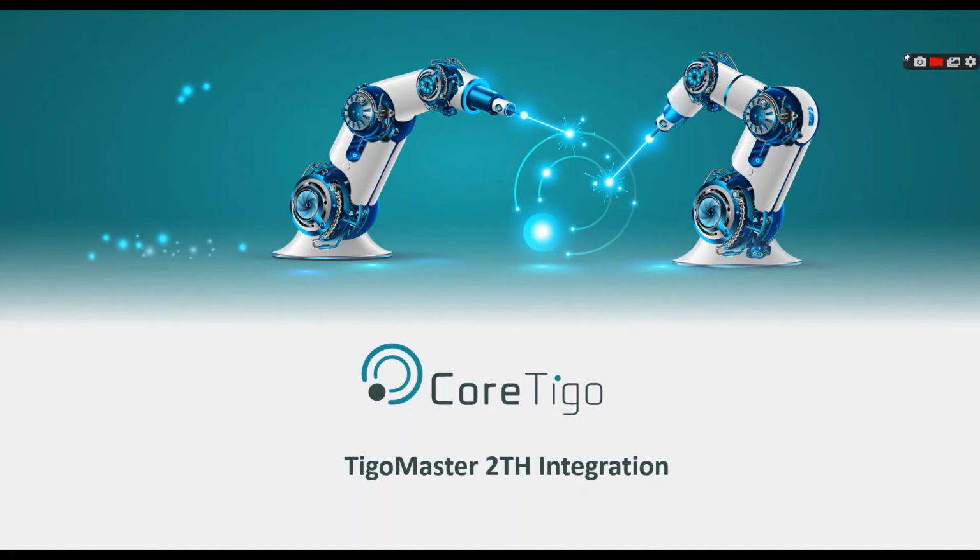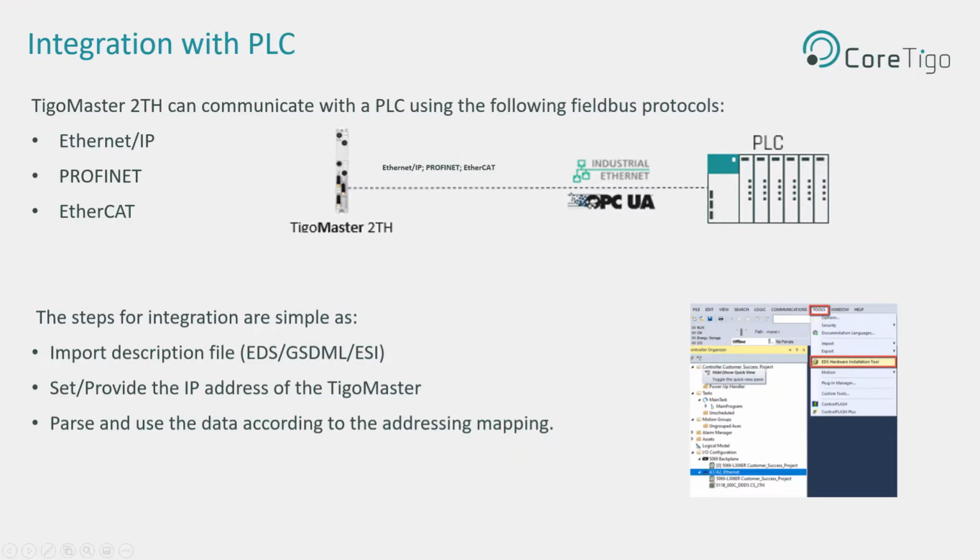In this video, we will see how we can easily integrate TigoMaster 2TH with a PLC. TigoMaster 2TH supports fieldbus protocols such as Ethernet IP, Profinet, and EtherCAT. The procedure is quite simple: importing the description file to the programming environment of the PLC. We will provide the IP address of the TigoMaster so that the PLC will be able to connect to it, and then parse and use the data according to the addressing.